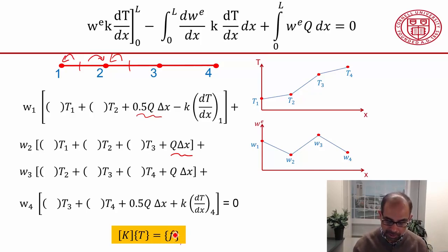It's the same thing. But what this means is that the heat generation or the source term is going to affect all the rows of F because it appears in all the equations. This is in contrast to this term that's going to affect only the equations at the boundaries. So that gives you some insights into how the source term gets incorporated into the algebraic equations.